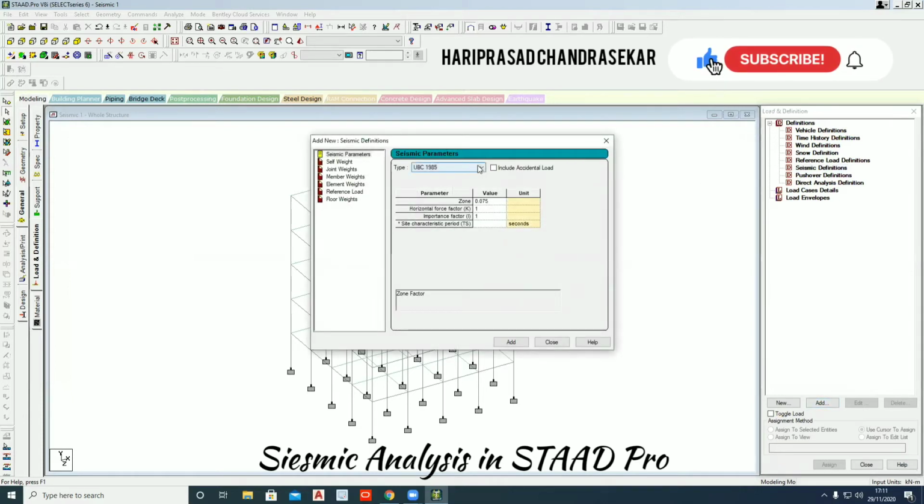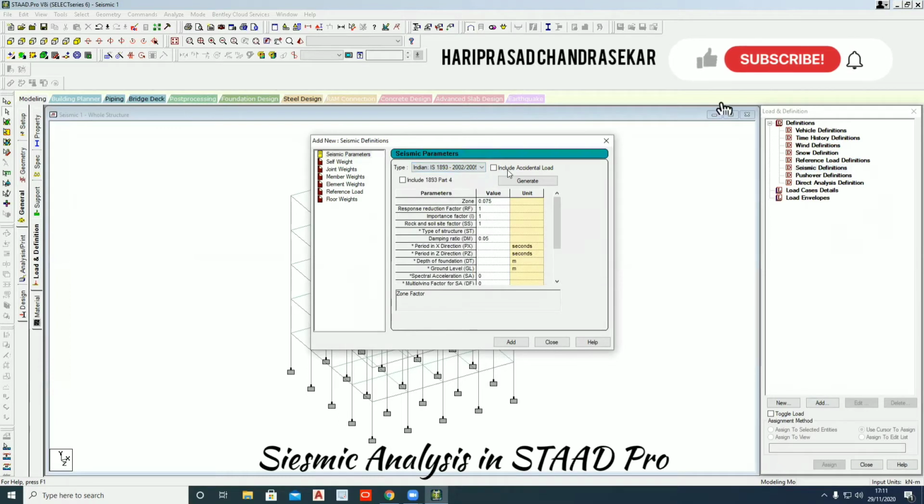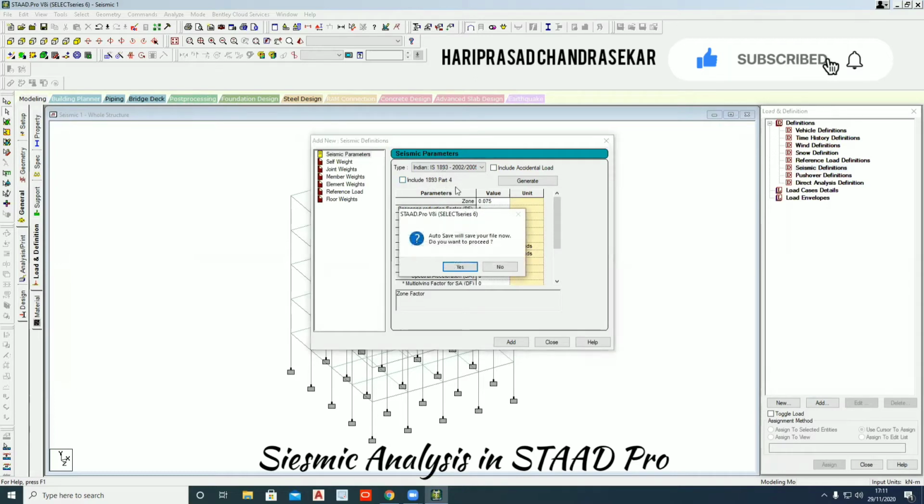And here I'm going to use Indian standard IS 1893 2002. You can choose any of that, but normally we use IS standards, and you can include accidental load or include IS 1893 part 4. Okay.